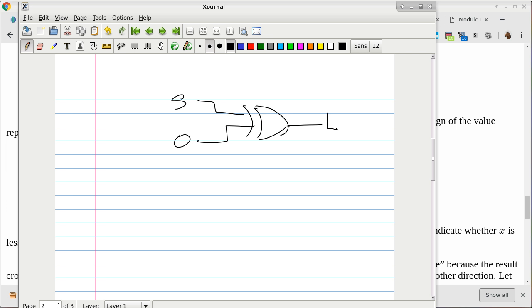Can I start the next lecture with the complete expression of the less than? L is really just the overflow XOR sign. Those are just the most significant bits. The sign bit of a number is the most significant bit of that number. So there's no equation for the sign bit because it's just taking the most significant bit out.